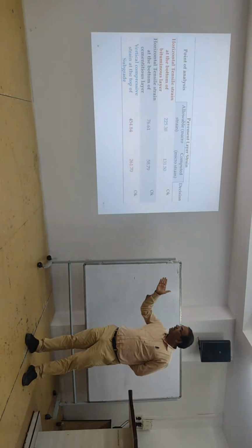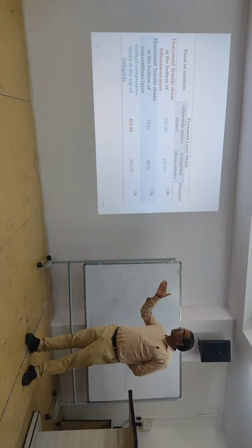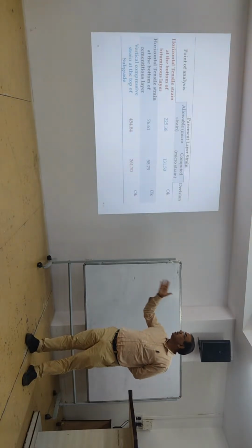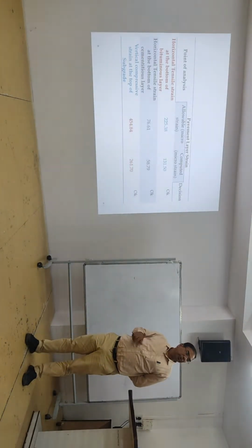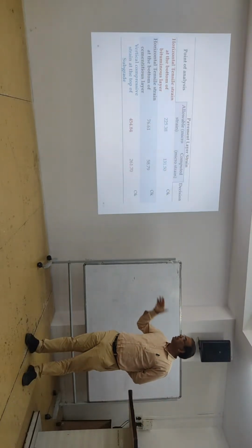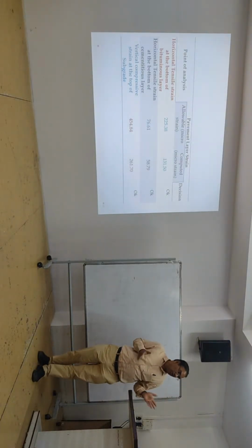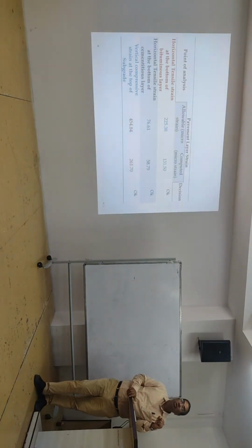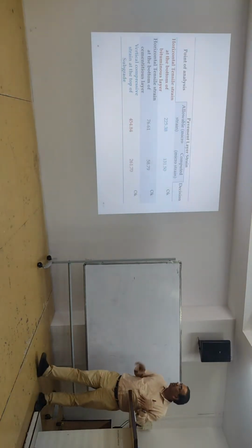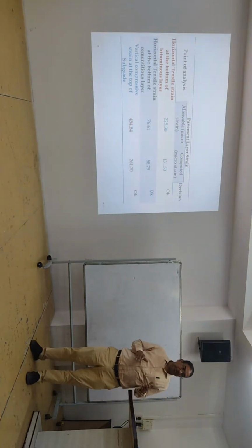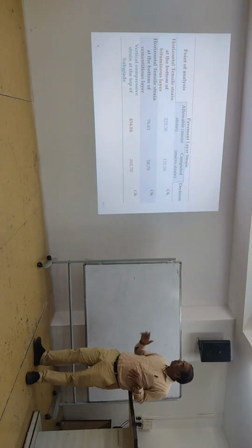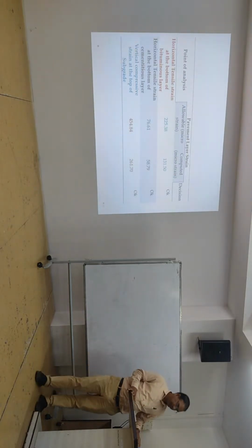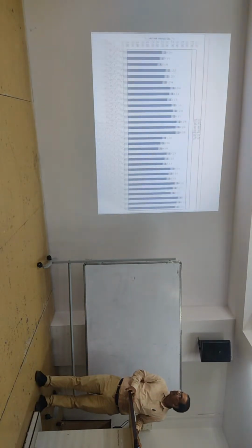So tensile strain, horizontal strain, and vertical compressive strain also have an allowable value of 450 micron, but we are getting 261, because the stiffness is increased, so your strain becomes less. Allowable is 450 micron, but we are getting only 261. So we can say that this is a pass. So the road is good. We can go ahead with the road construction.